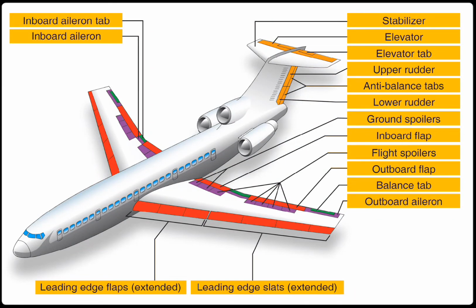What are the three types of commonly used flight control systems? Cable, push-pull tube, torque tube system. What is used in large metal aircraft to keep control cable tension within acceptable limits? A cable tension regulator.